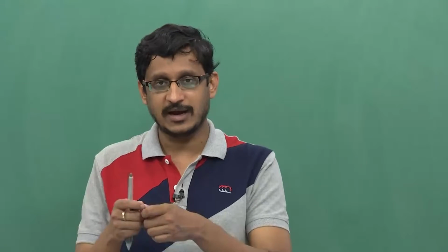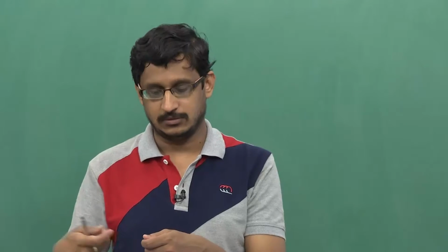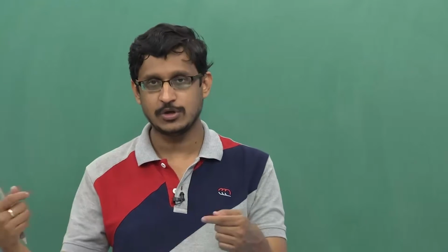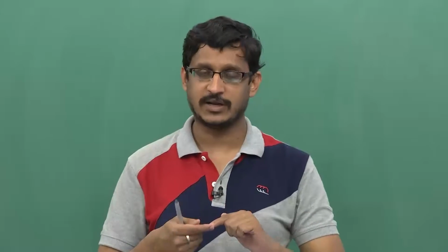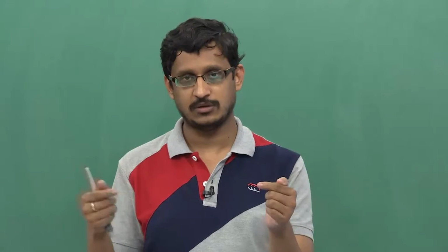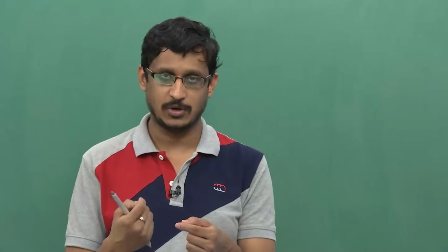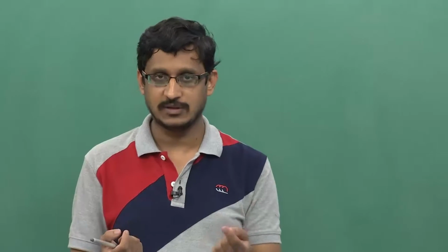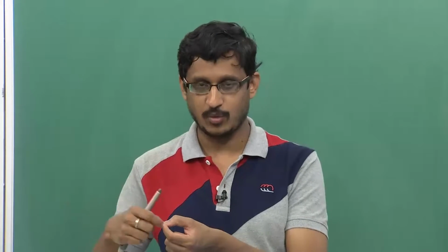We are now connecting that fiber to the actual transmission fiber. When you have to connect two fibers, you have to use what is called a connector. We will see some types of connectors later, but for now connector simply means I can connect light from one to the other. Then I have the transmission fiber through which the signal propagates. As we know, the fiber induces loss in the signal that is propagating. So, the power keeps going down. At the output end, you have to connect light again to the optical receiver via one more connector.